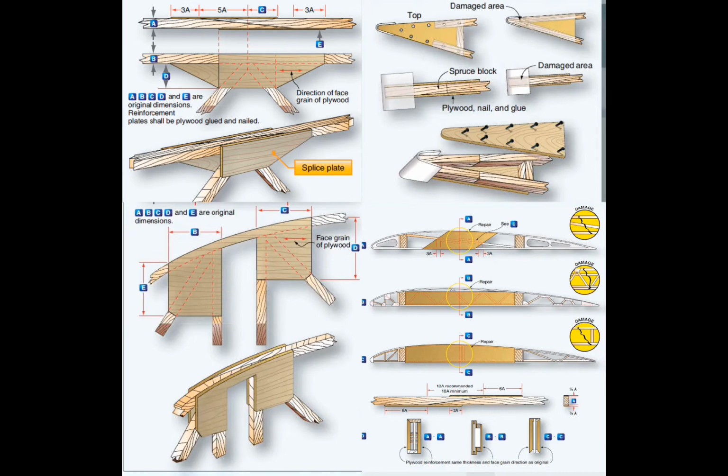What type of patch is preferred for repair of stressed plywood skin and why? A properly prepared and inserted scarf patch is the best repair for plywood. It uses reinforcements under the patch where the glue joints occur.